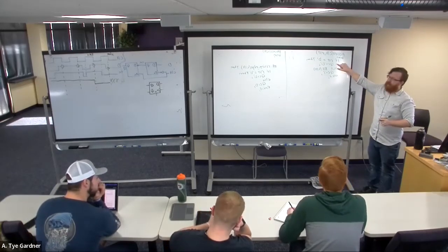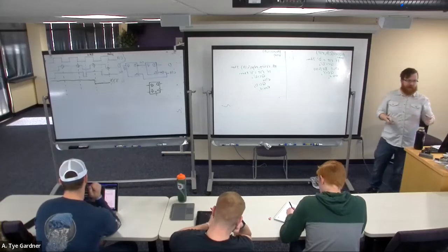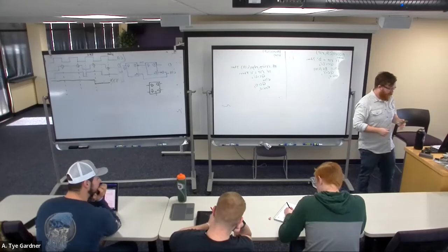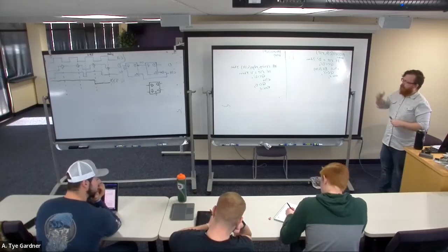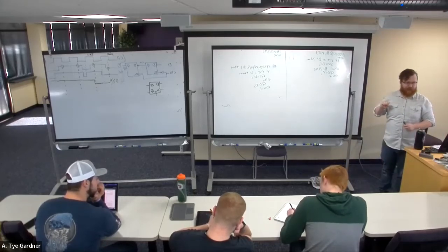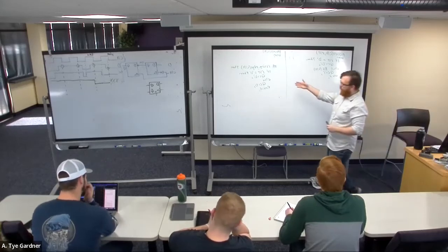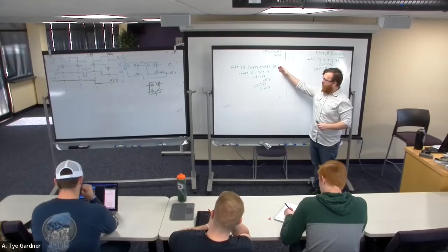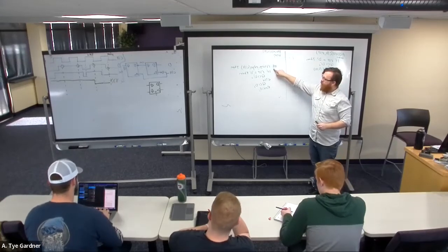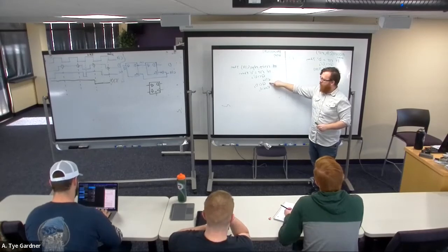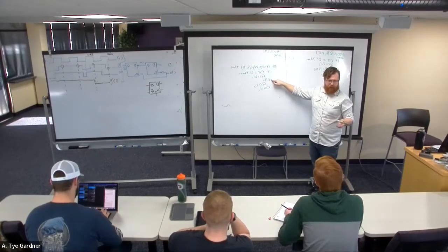Now, there is something that you need to be very aware of that I often forget to teach, which is unfortunate, which is that the order of your if statements matters. So over here, if I said, if rising edge of clock, if reset equals 1, then Q equals D, else if 0, that's probably okay because the reset condition is taken care of.